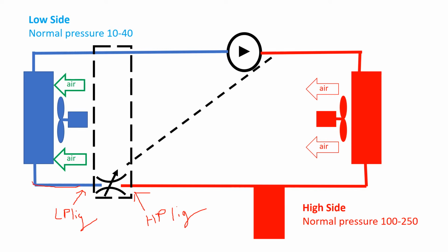As that refrigerant winds its way through the evaporator, it absorbs heat. And by absorbing heat, that refrigerant will become a vapor as it exits the expansion valve and evaporator. I'm not going to put a question mark on vapor here. We must have vapor here because there's nothing between the outlet of the evaporator and the inlet of the compressor other than a rubber hose that would allow any liquid to absorb heat and turn to vapor. Reminder again, AC compressors do not like liquid refrigerant. It's hard on the reed valves.